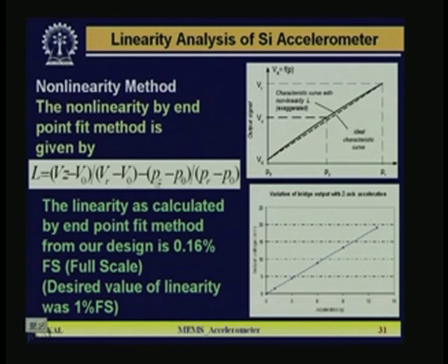Say this is a plot versus input, where P is the input variation and the output is always the voltage variation. So, P naught to Pr is the change; here V naught to Vr is the output, on an arbitrary curve, and P naught to Pr is the input change. Your ideal characteristic is linear, which is shown by the dotted line, but your real curve, obtained from experiment or simulation, may be like the solid curve. So, the solid curve and the dotted curve have got certain deviation. How much deviation? That is basically the linearity.